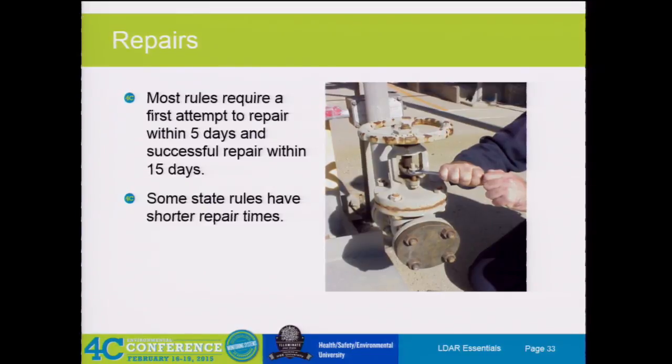We've actually seen folks in California, the South Coast, that doesn't even allow DORs. They'll actually bring down a process unit to fix a big leak because they can't put it on a DOR. I've only known of one site that's gotten away with one DOR, and it took them a week and a half to get justification of why, and they were granted it for about a month because they were coming into a process unit shutdown at that time. So some folks are very unlucky.